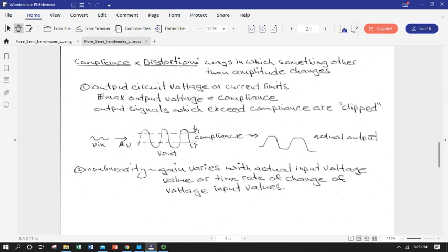And at the end of the day, what that says is we've got a finite range of voltages that we can actually push out of the amplifier. It's limited by the DC biasing limits. So what that's really going to mean is if we have a given input signal and we apply some voltage gain through our amplifier, which we're usually hoping to do with an amplifier, we could get a very high amplitude output that we want, but we will only actually be able to achieve what's within these two dotted lines. And that's actually defined again by our DC load line.